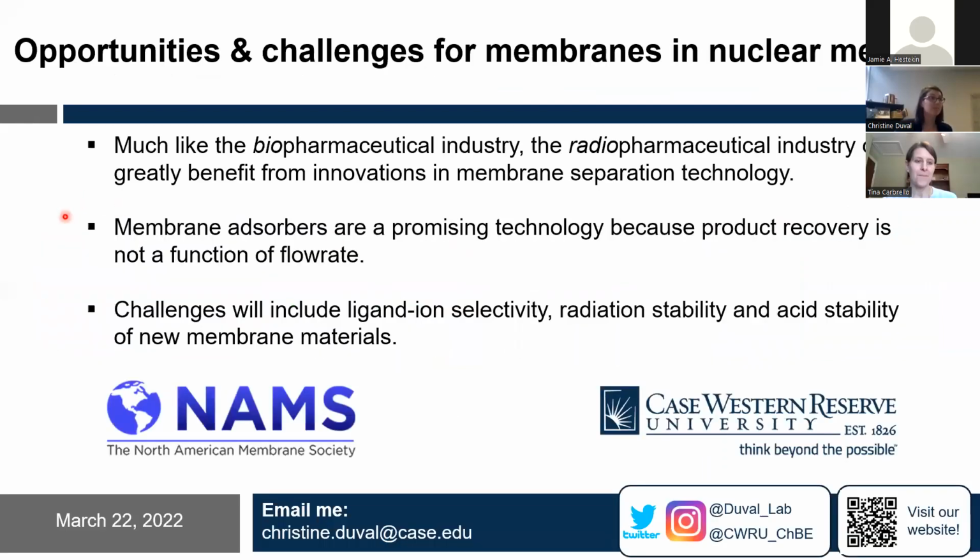So there are some opportunities and challenges, right? Much like the biopharmaceutical industry, the radiopharmaceutical industry can really benefit from innovations in membrane separation technology. In particular, membrane adsorbers are promising because product recovery is not a function of flow rate. And maybe there's some debate in the biopharmaceutical industry whether or not they need to go to extremely high flow rates. I'm not sure it's as necessary for them as it would be in radiopharmaceuticals, where your product is decaying away. So you have a legitimate time constraint that you need to consider when doing your purification.